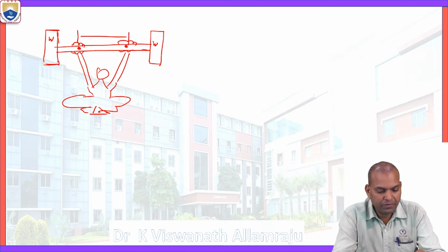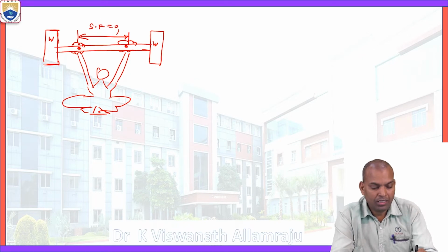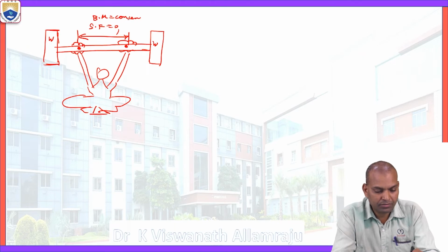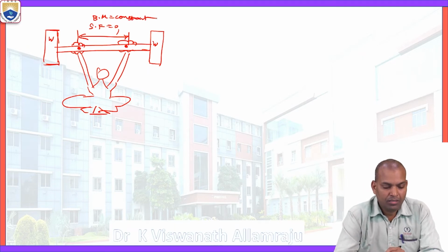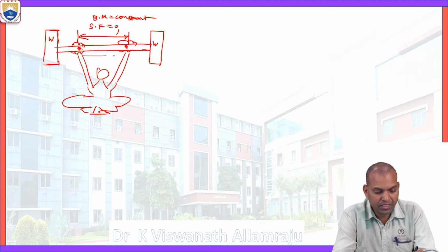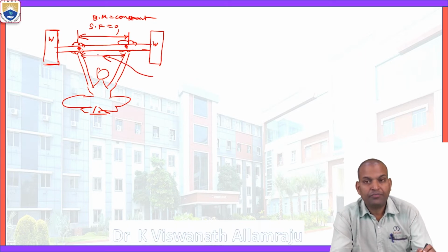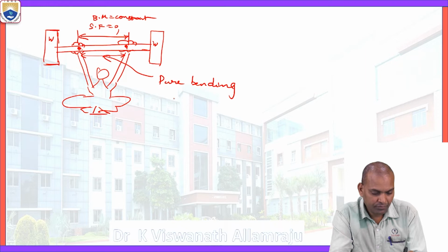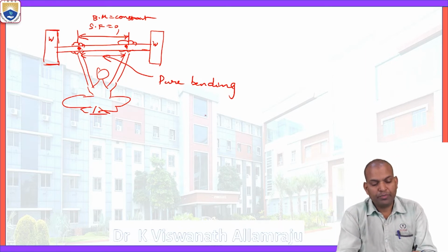Between the supports, the shear force is 0 and the bending moment is constant. So this is the application of pure bending. Between two supports or two places, the bending moment remains constant, and this portion experiences the pure bending phenomenon.